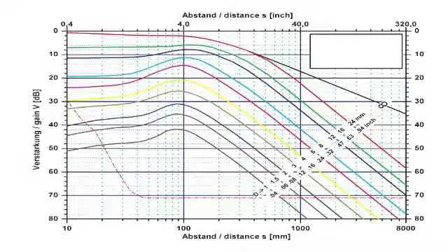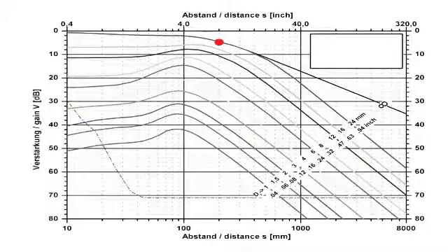As an example, let us assume that the back wall of our workpiece is 200 mm in depth and produces an indication on our ultrasonic flaw detector, which needs an instrument gain of 32 dB to be brought to 80% screen height. The back wall curve is marked at a depth of 200 mm, and we keep the gain of 32 dB in mind.